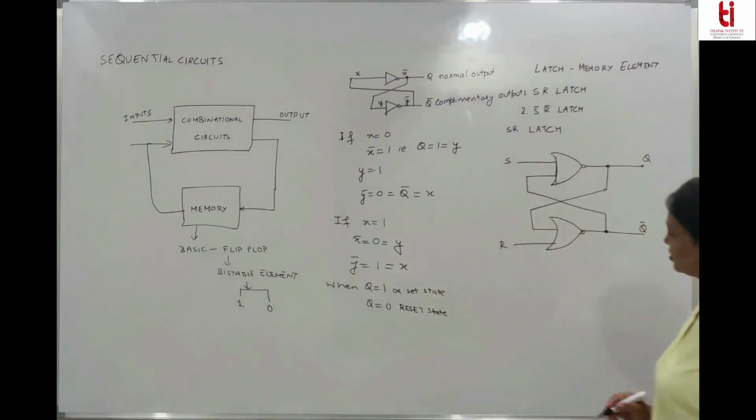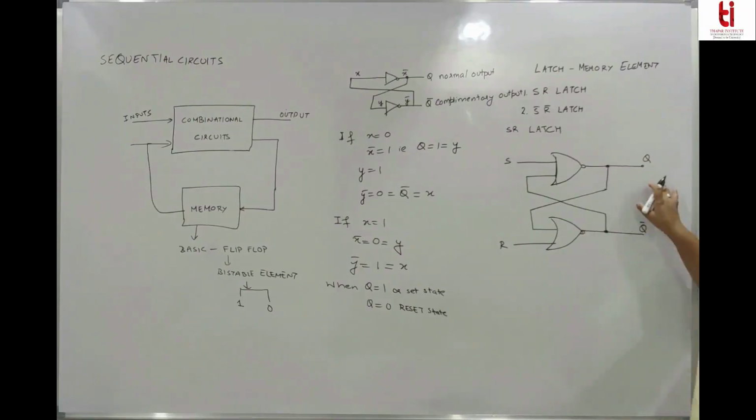This is an SR latch. You can see the output is basically not time dependent. There is no time period, there is no control signal, there is no enable signal. It is totally dependent upon the input signals. So this is the basic memory element which is being used everywhere. It is called a latch. There is no control of the input, no control signal, no enable signal, no clock, no time period.